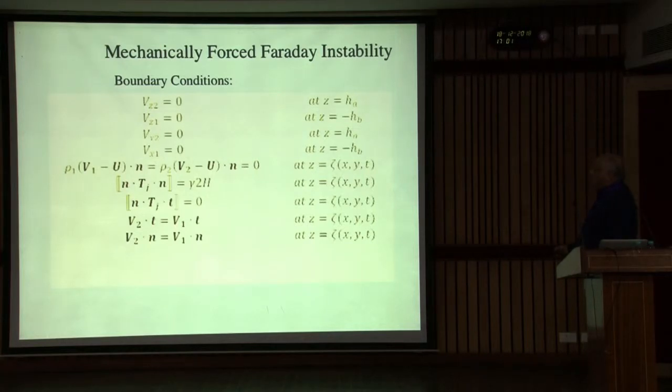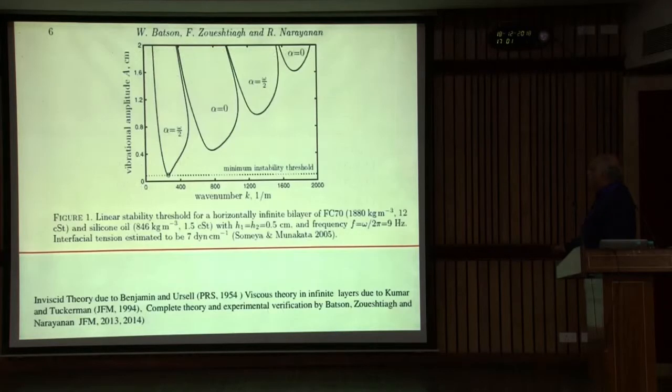And so let's go over the boundary conditions. They're also fairly simple. The first 4 are simply pointing out that you have no flow and no slip at the top and bottom walls, but the most important boundary condition is actually the normal one.